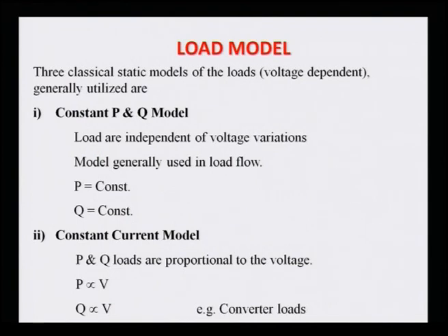So, loads can be classified into three static load models. One can be your constant P and Q model, where the loads are independent of voltage variation. More generally, I can say they are normally used in the load flow analysis, where the P and Q are treated as constant. So, this is the constant P and Q model.